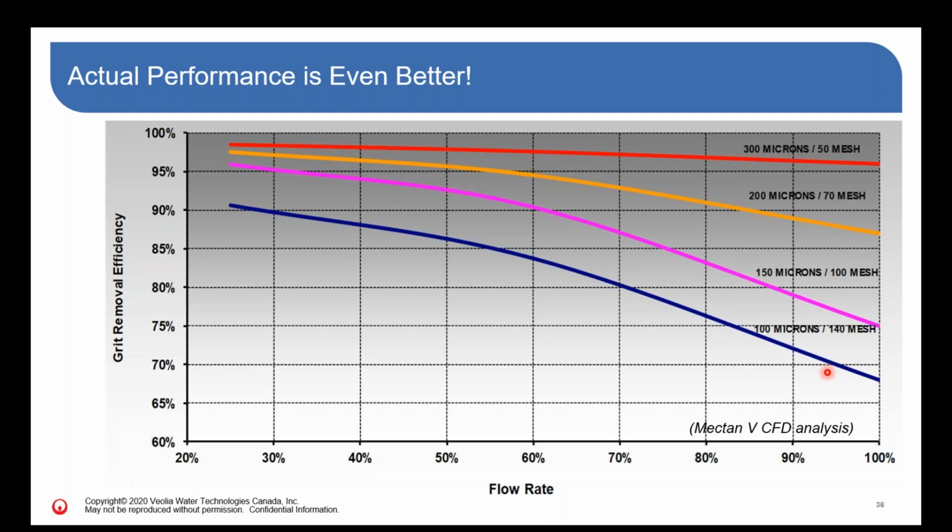Because units are typically sized for the peak flow at the plant, peak hour flow typically, it's a headworks product, but also the project is likely to stipulate that flow on a future design horizon, maybe 20 years into the future or whatever. What you're going to find is that typically the unit is going to be operating down here somewhere.